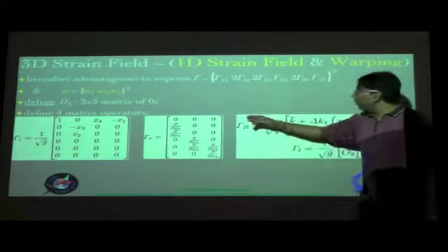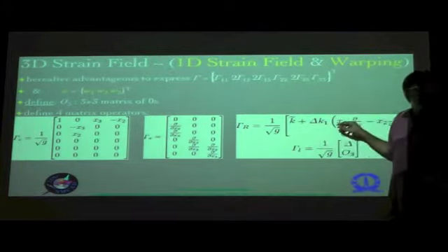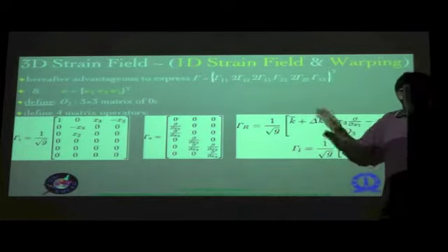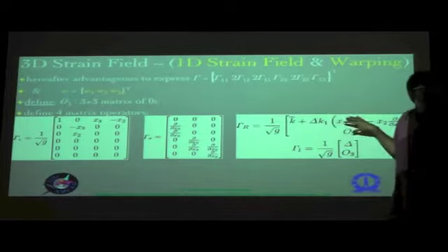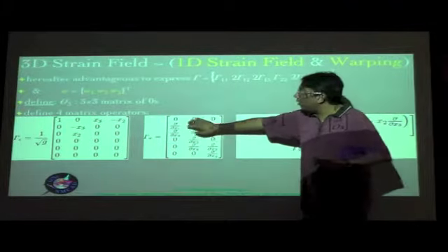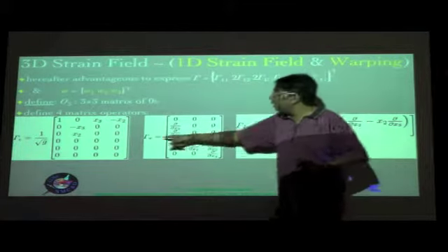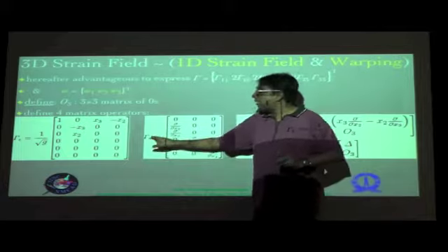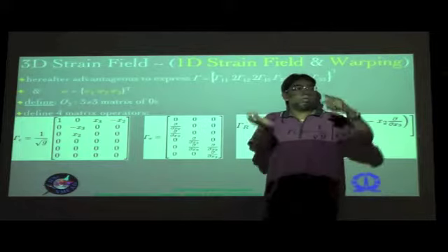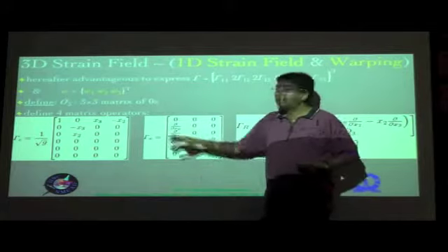One is contribution purely because of the initial curvature and initial twist or pre-twist that you have in the beam. So if there were no pre-twist and if there were no initial curvatures, then the contribution from this particular term would go to 0. So leave that aside. Then you have a contribution from warping because of the derivatives with respect to the cross-sectional coordinates, which you define as gamma subscript A, and A, remember, is the variable that we are using to refer to the order of magnitude of the characteristic cross-sectional dimension. So that is a mnemonic to remember what this is associated with.